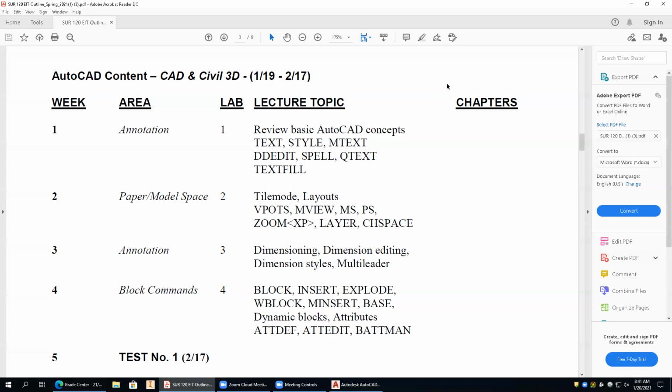And then there's this other little system variable called TextFill, which is pretty cool. And what that'll do is give your text a hollow shell look. So it just has the outline and it gets rid of the fills. So I'll show you how that works. Now that one's a little nasty one because if you turn that thing on, you never see it that way on the screen. The only thing that sees it is the printer. So unfortunately, you can have that on all the time and never know it. So you got to be careful with that little guy.